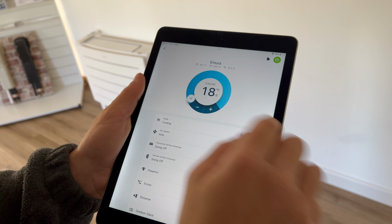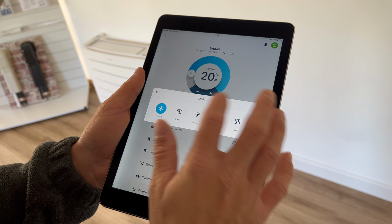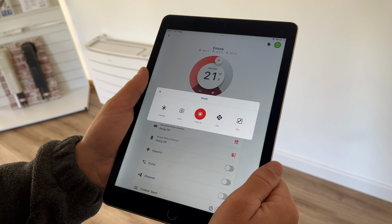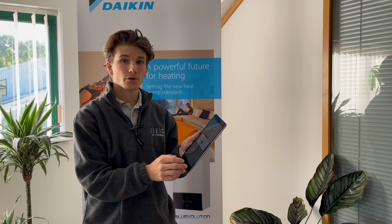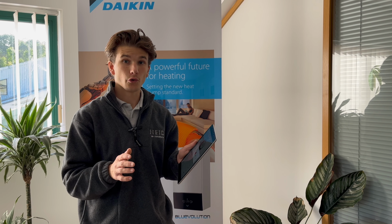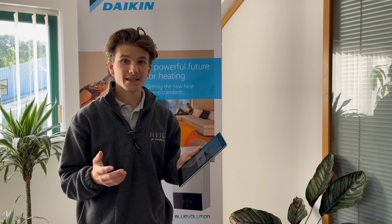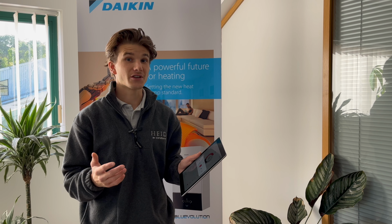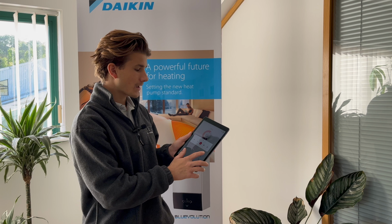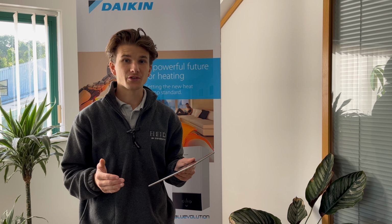to your desired temperature. To change the mode, you press the mode button and you can see all the options here. So you can select between cooling, auto, heating, fan, or dry. In auto mode, the system will decide whether it needs to do heating or cooling to get to your desired temperature. In fan mode, it just runs the indoor unit fan and not the outdoor unit, so there's no change in temperature, it just circulates air around the inside. And then dry mode is dehumidifying, which uses the evaporator to draw moisture out of the air.